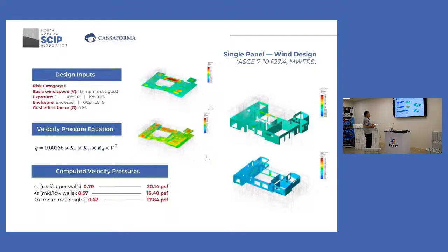Of course, we had to take all the codes. We have to see the wind loads, how they are, the risk category. Here, unfortunately for us, in southern Florida, you have to check every single opening. For Miami-Dade County, you have to go over that, and that's a little painful, but you have to go through it. Also the manufacturer has to confirm that he has the correct anchor for that.